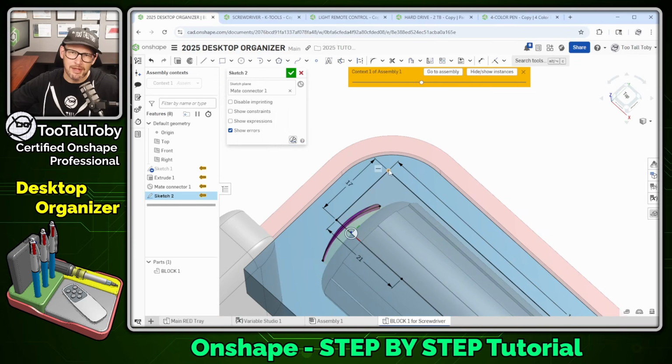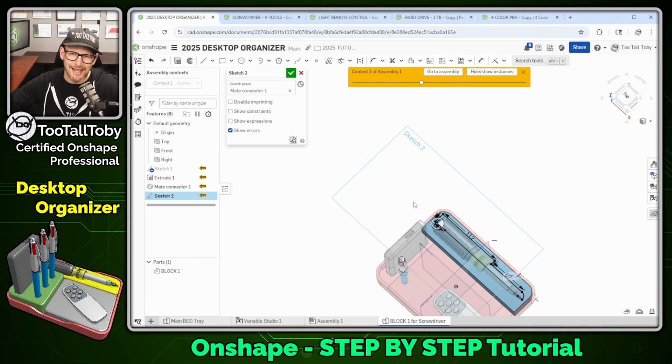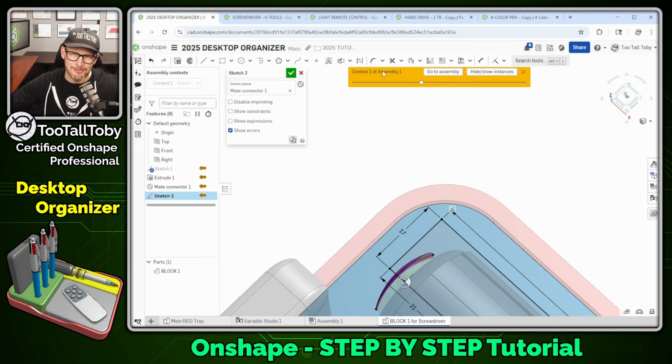Like, maybe I would put in a fillet up here in this corner, and maybe I would put in some other little detailed features on this part. In fact, I might make a fillet there anyway, just because I don't want it to end up protruding outside here. So maybe I will add that fillet. So I'll click on the sketch fillet, click on that corner there, and let's give that a radius of 6 millimeters. Okay. Good. We're done with that sketch.